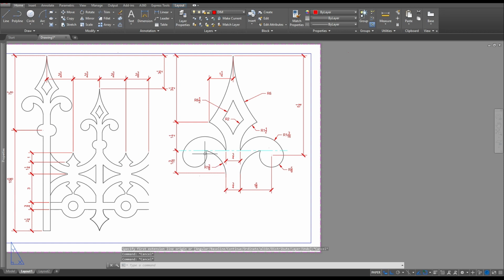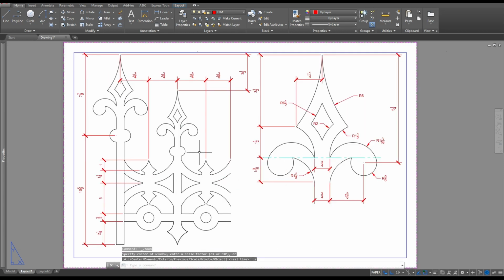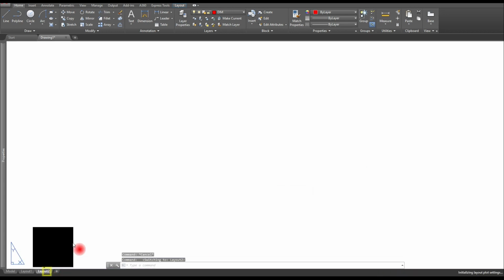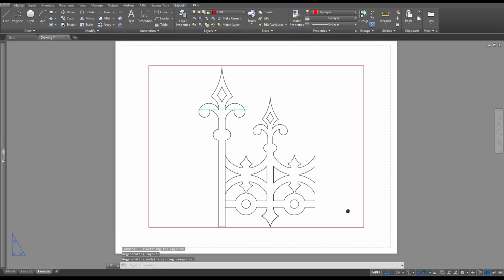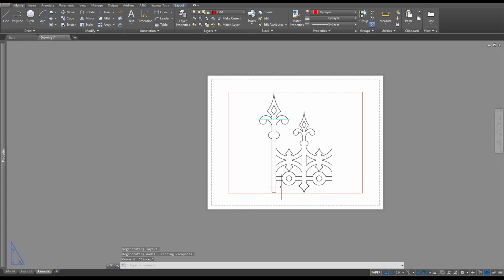Alright, so all my dimensioning is done on this page of everything that I'm going to need. I can jump over to the next page and finish that. So I'm just going to switch and open up the one in Layout 2. I can create that rectangle again. So rectangle 0,0 to 17,11, just offset 0.5.